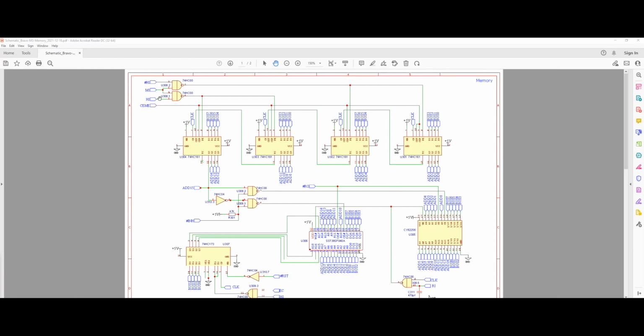By default, when we turn on the computer, the HI signal is low and the inverted HI is high. So if we bring the MI signal high, those two signals go to two inputs on a NAND gate. If we have a high on both of those inputs, the output of this NAND gate will be low.